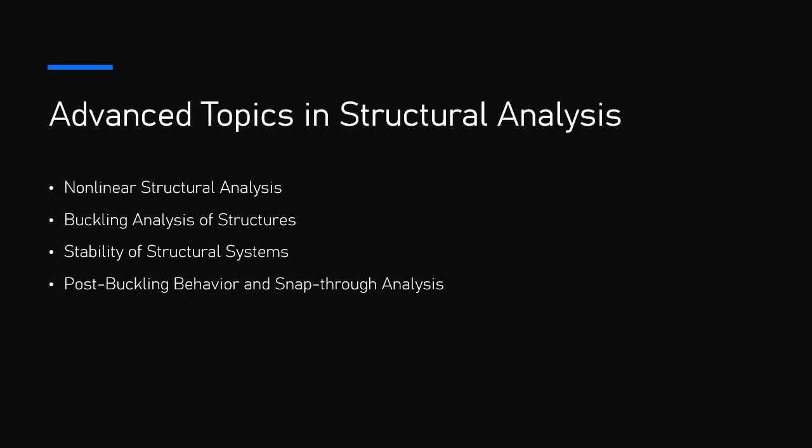2. Load deflection curves. Engineers use load deflection curves to assess the behavior of a structure beyond buckling. These curves show how the applied load and displacement evolve through the buckling and post-buckling regions. In stable post-buckling behavior, the curve shows an initial drop in load followed by an increase or flattening. In unstable post-buckling, the curve shows a significant load drop or sudden failure after buckling.